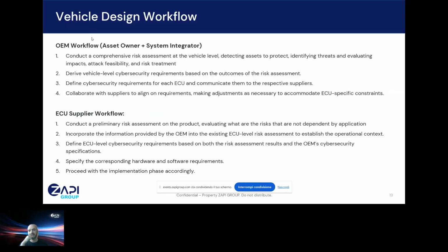And in this case, the OEM needs to start from the risk assessment on the vehicle. From this risk assessment, it needs to define the cybersecurity requirements, and it needs to provide to the supplier the cybersecurity requirements for the specific ECU.